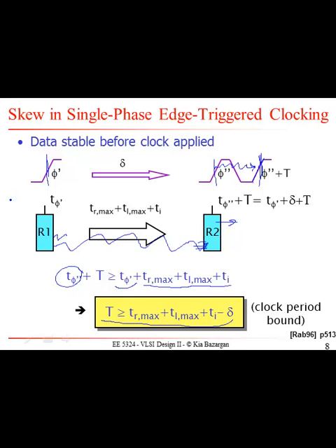So if your clock signal is being routed in this direction, then you would get the clock first here, and then with some delay you would get it here, right? But that doesn't have to be the case. I mean, your clock driver could be here driving this guy, so this could actually come sooner than the edge that you would see here, right? So in that case, we're going to say that your delta is going to be negative.